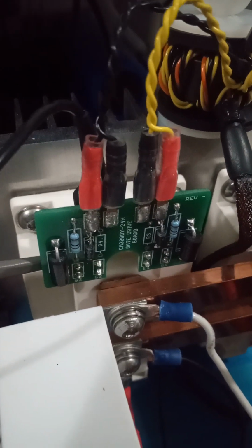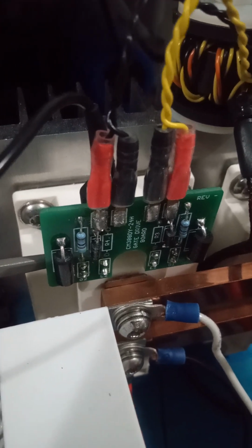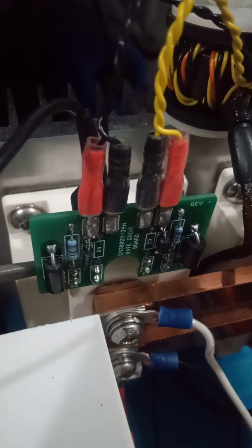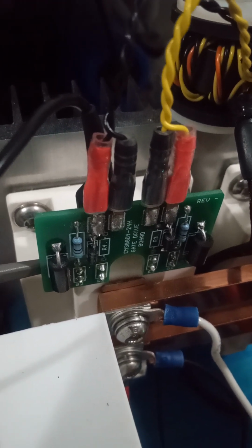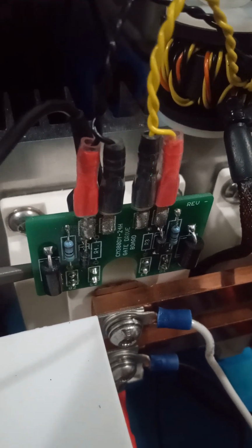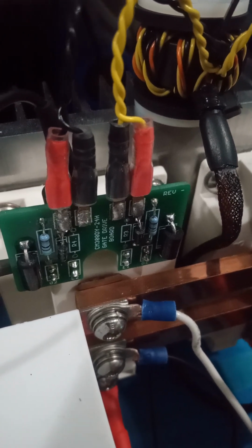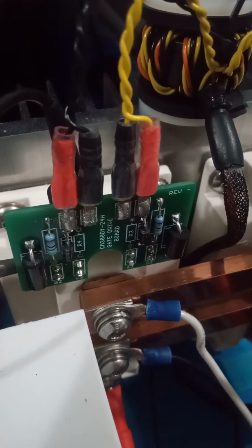Now, whichever one is positive, so if you want the gates to switch on, then you're going to put the positive where your lead is from your oscilloscope on that wire, and whichever one is positive, you're going to connect it to your gate for switching on. Your negative is going to go on your emitter for positive. Now, for negative or off switching, you're going to connect your negative lead to your gate and your positive on the emitter. So that's going to be switching off, which I'll show you guys just by switching those connections on your oscilloscope.